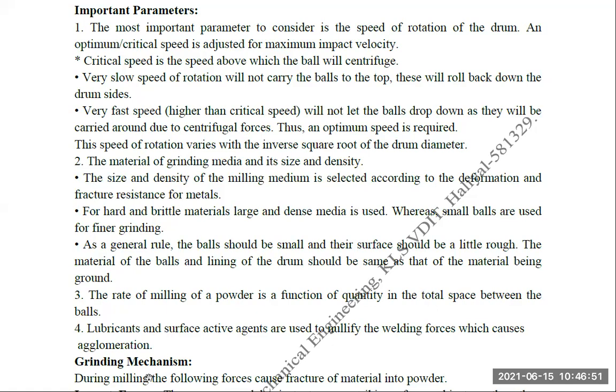Here the grinding media material, its size and density. The size and density of the medium, whatever we are going to use, should be chosen with respect to deformation and fracture resistance. So certainly for hard and brittle materials, large and dense media is going to be considered. Small balls are going to be used for the grinding purpose.